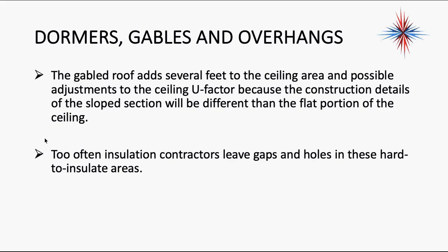When you have a vaulted ceiling that's sandwiched right up against the ceiling joists, contractors sometimes forget to put insulation between the vaulted ceiling and the roof. How would you figure out that the insulation's missing? Two easy ways. Would you feel the wall where it would be connected? Well, yeah, I wasn't even thinking of that.